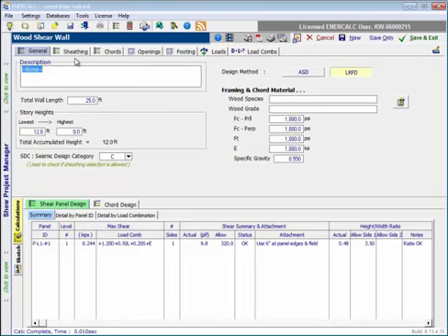And then as we look down the line through the normal workflow progression, we can see that we'll have a tab that will collect information on the sheathing that we want to use for this particular shear wall, information about the chords of the wall, information to define any openings that may be present, an option to define a continuous footing underneath the full length of the wall if desired, a tab that will allow us to define the loads that act on the wall, and finally a tab that allows us to define our load combinations for the different types of analyses and design that will take place within the module.